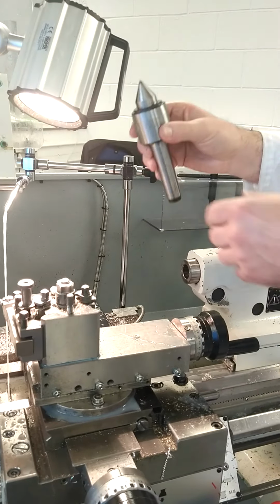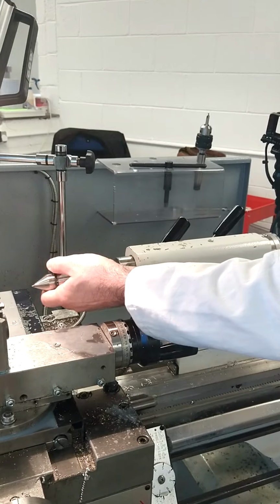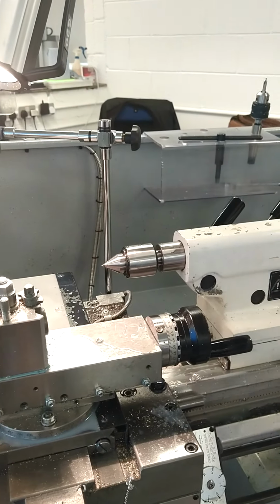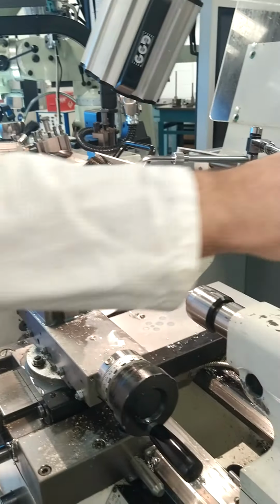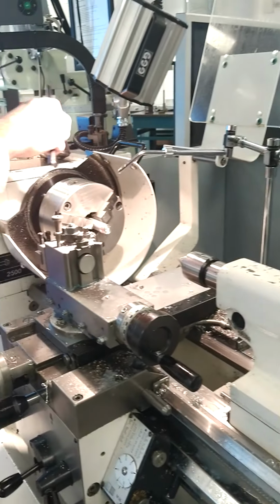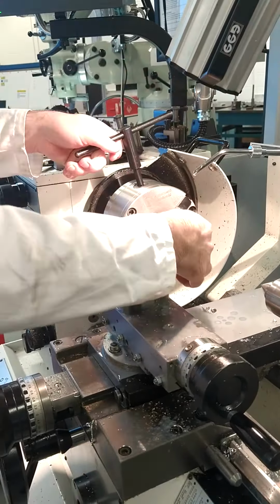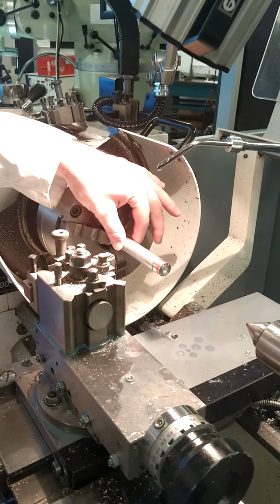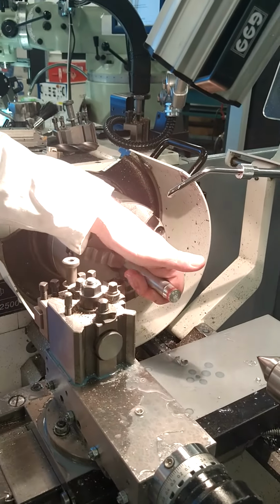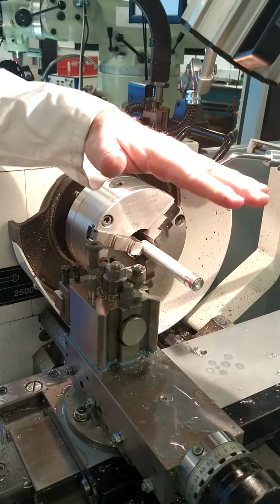So now we can pop in the revolving center. So another use of the revolving center is support work. So supporting work, what I mean by that is that we're going to be able to extend the work out now. Because we've got a center, it allows us to extend the bar out from the chuck, and it's very important that you always support the work when extended out more than 3 times its diameter. So meaning that if the bar is 20, once it goes past 60 millimeters of an overhang, you have to support the work, otherwise it'll be oscillating up and down.